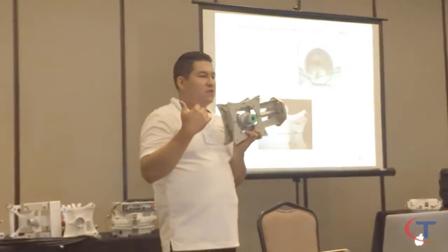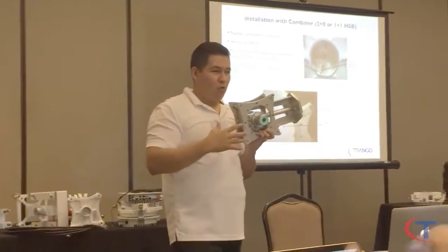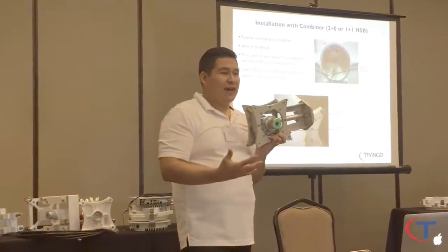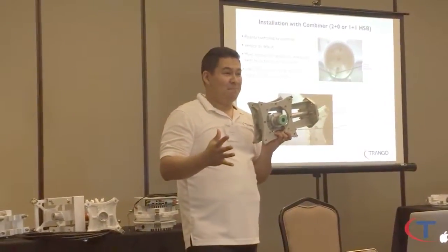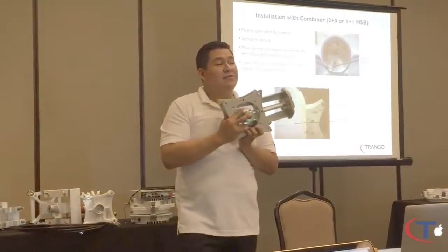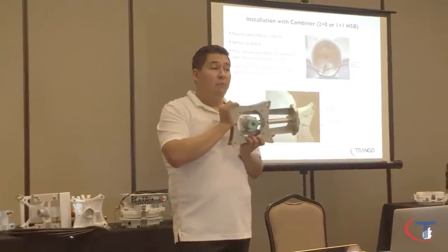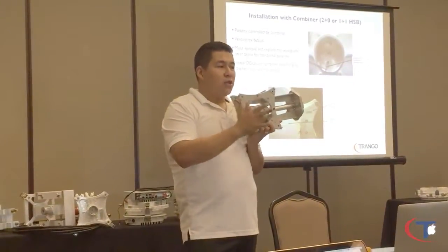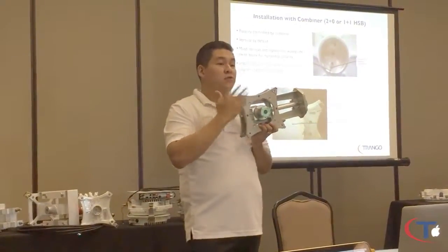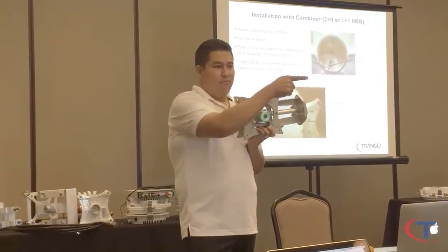I've had this happen a couple of times to customers. They cross-polarize all four. They get a good RSSI, but nothing locks. So this happens quite a bit in the field. I'm going to pass it around. And again, remember the rule of thumb: when I'm using a combiner, make sure the ODU matches the internal polarization of the combiner. Like a slit like this, make your other slit like this. Correct.